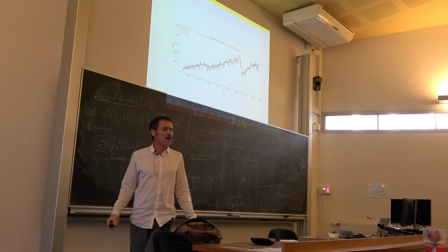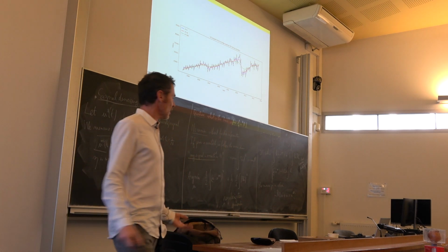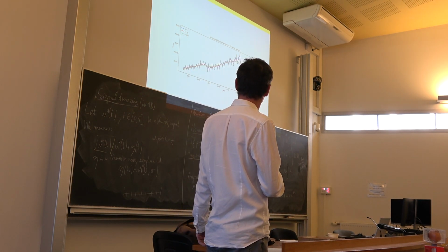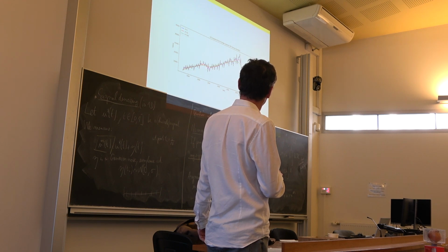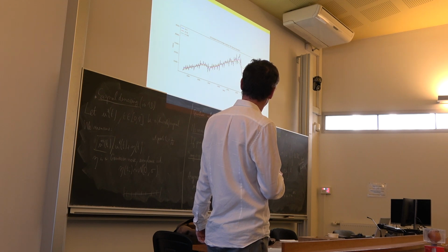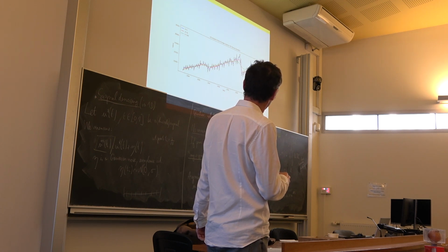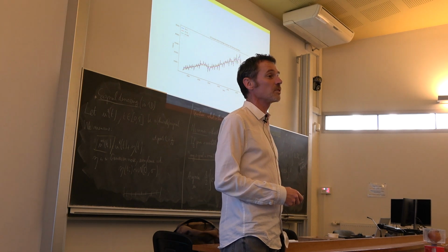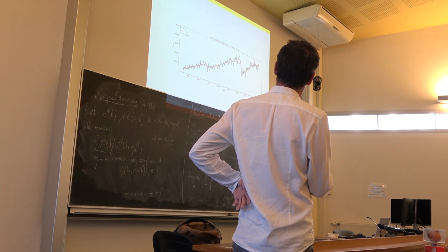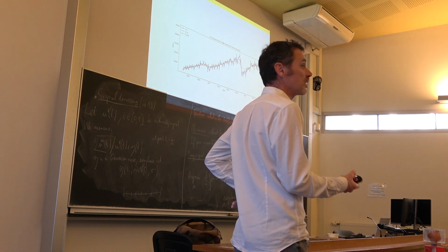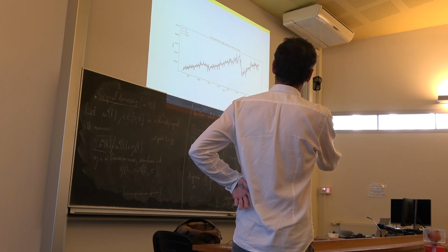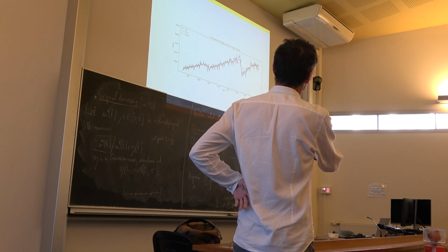So I can say, well, I want to increase the smoothness of my curve. I take lambda equal 10. I have the red curve, and it is still oscillating a little bit. Okay, I take lambda equal 100. Now it is very smooth, but you had to pay for something. Here there is some kind of discontinuity. You want to believe that the discontinuity is present in your signal, but by smoothing, you lost the discontinuity here.